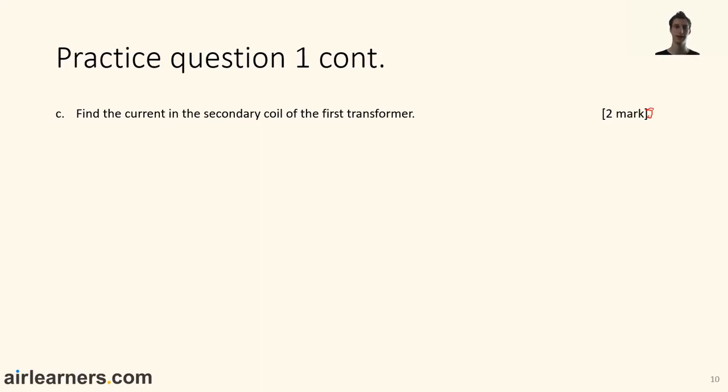All right. Now that you've hopefully had a decent attempt at this question, we can run through the solution. So what do we have? I'm going to whip out the classic equation that we need to use. So we've got the input voltage over the output voltage is equal to the output current over the input current. That follows straight from the turns ratio. You substitute that in, and we can find our input current.